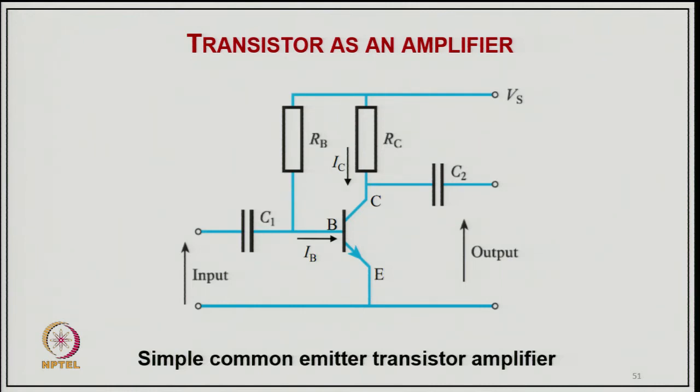So, we have an input AC, we have coupling capacitors on both sides, and of course, biasing from the supply voltage to the base, as well as a resistance in the line to limit the current as the transistor goes towards amplification.